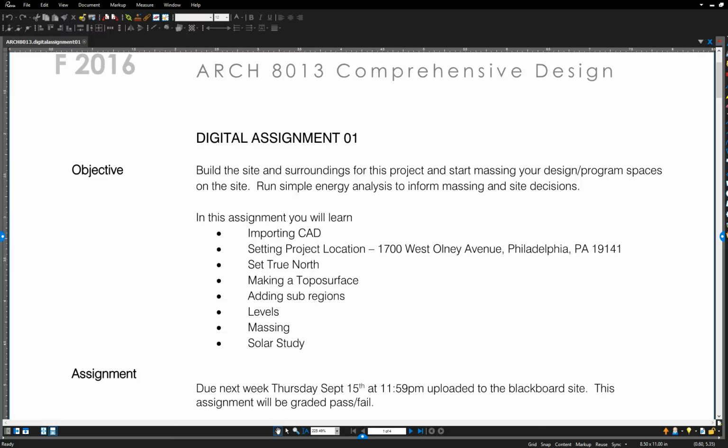This is the video for Digital Assignment 1 of ARC 8013 Comp Design. In this digital assignment, we'll be going over how to get your project started in REVIT. That's going to include importing an AutoCAD survey file as our base, setting the project location to be the correct location for the project, setting north to be correct based on the drawings that we import.